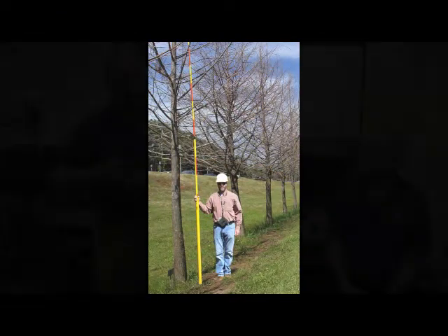So we randomly selected a number of trees that are representing the trees on the SFA campus. And then for each tree, we take measurements with pictometry, and then we send our students to the field with a height pole, reaching out to the very top of the tree to get the exact measurement of the tree. And then with a good number of samples, we are able to run some statistical analysis to verify whether there is any significant difference between pictometry measured height and the real on-site measurement of tree height.